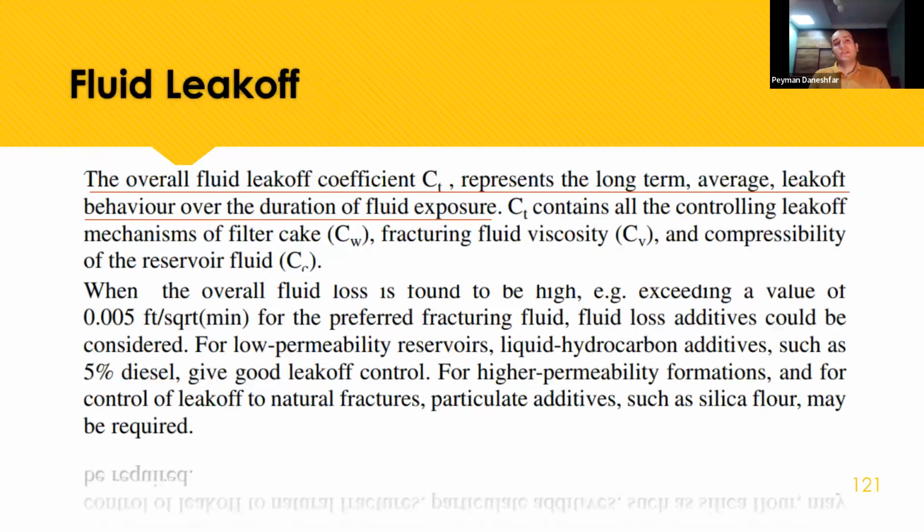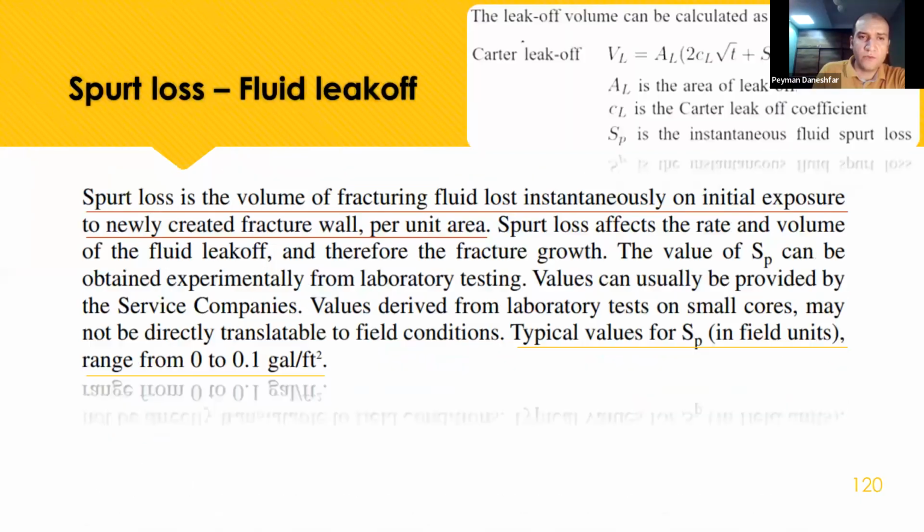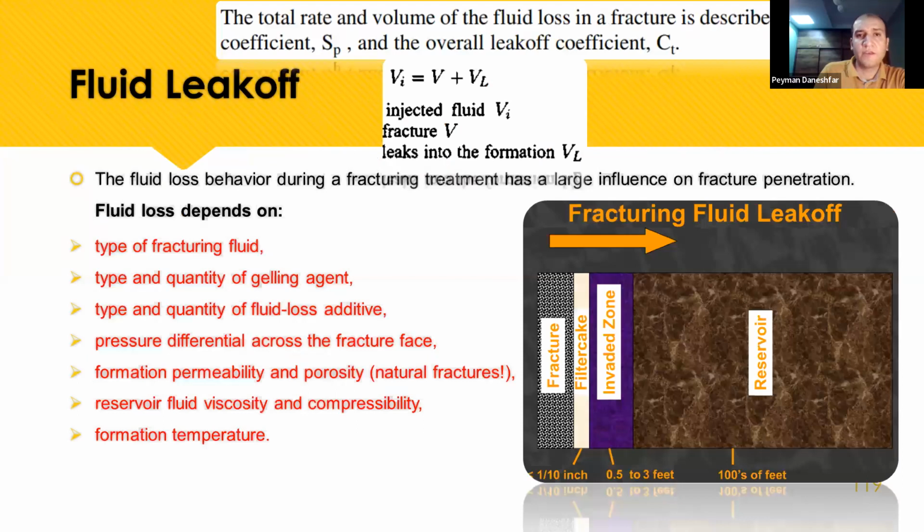The overall fluid leak-off coefficients represent a long-term average of leak-off behavior over the duration of exposure. Again, always to tell you this formula: volume of injection, volume of fracture, and volume of leak-off. So the volume of leak-off is so important for us, because when we want to calculate the